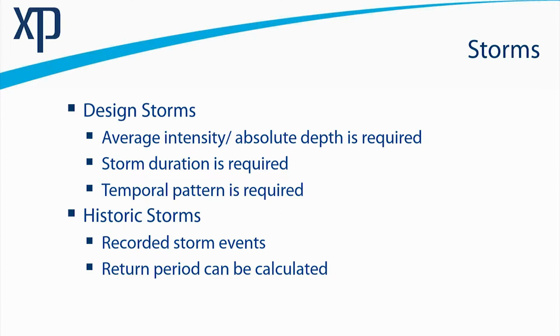I need to assess a range of storm durations. This sort of approach, this design storm approach, is not an equivalent to the rational method. And I'll talk a bit about the rational method shortly, but it's not a situation of modelling simply one storm duration. We need to assess a number of durations. And the temporal patterns do come from the MSMA2 documentation, which is a great reference manual for the Malaysian region, and I hope that everyone either has a copy or is familiar with that document.